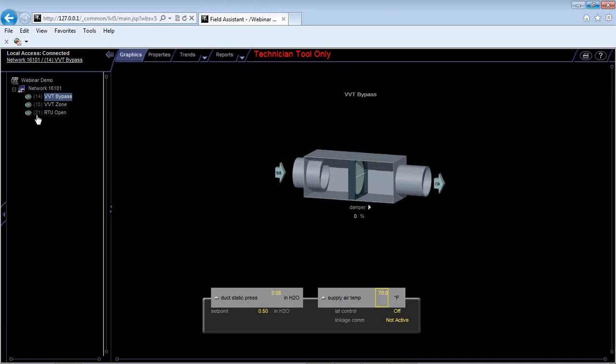Well, master controller and slave controllers. The master controller pulls all of the slave controllers for their information, collects it, and sends that data to the air source or rooftop unit. And then from there, the rooftop unit will decide if it should go into heating, if it should go into cooling, if it should just go into fan.